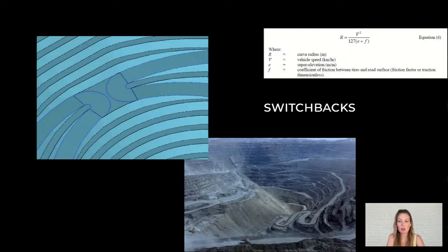When designing the turning area, it's important to place it on a horizontal intersection to ensure it has significant radius so the largest dump truck can maneuver without crossing into the opposite lane. To determine the required radius of the turning area, you can see the provided formula. And in summary, while switchbacks are sometimes unavoidable, proper design is essential to maintain efficiency and safety.